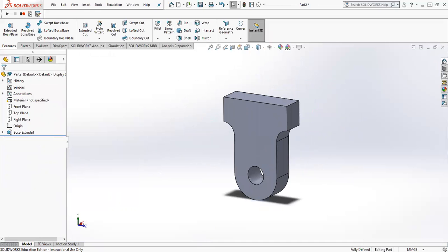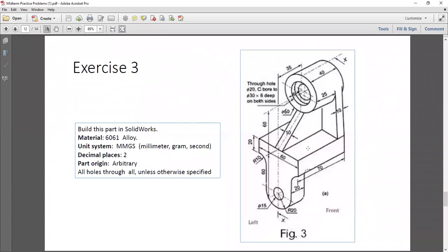All right, and then we are going to draw or do this portion right here. So we'll draw a rectangle on the back of this face, this planar surface, and then extrude that by 70 minus 20, because we see the 70 line right here to right here is 70, and then this is 20. So 70 minus 20 is 50. So let's do that.